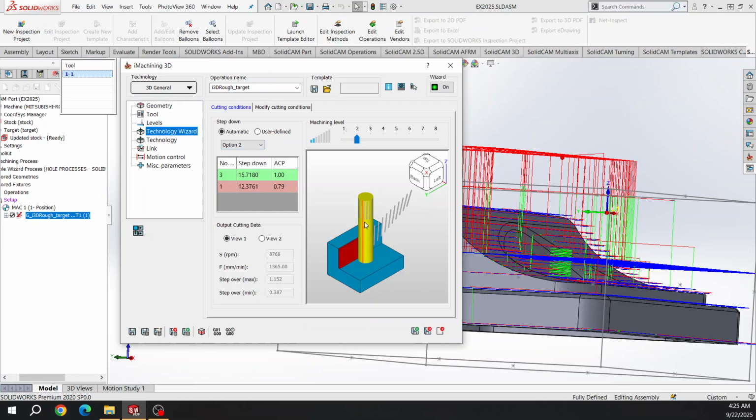You utilize most of the cutting surfaces of the tool. Normally industry people say this is much more efficient than going one operation at a time. iMachining gives you more efficient cutting, and also a very fast operation, which means you can remove the material very quickly.